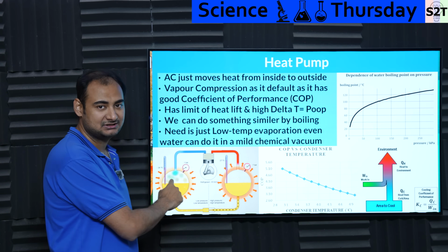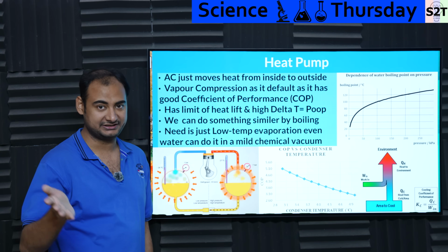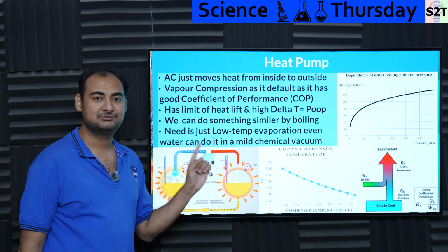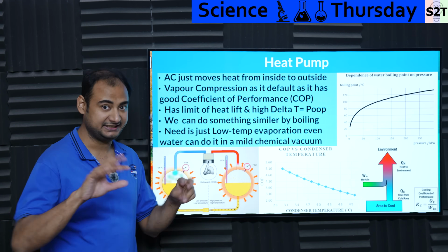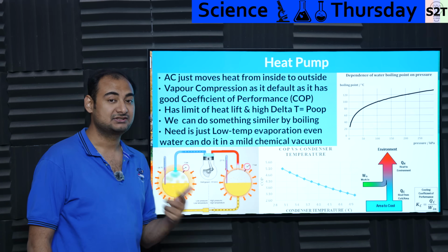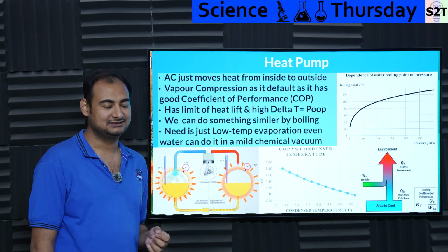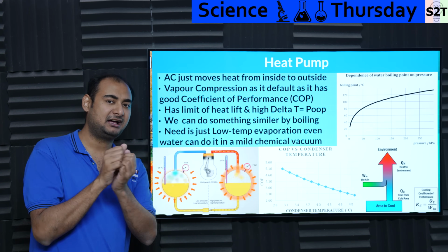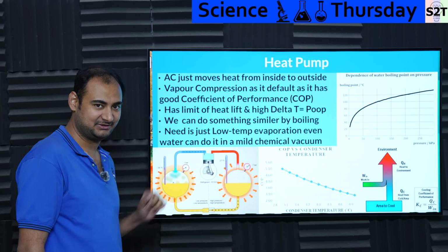Now the heat here was barely room temperature. The heat here is elevated, like 30 degrees, 40 degrees Celsius. At that point in time, you run the fan, it dumps the heat, and voila, now it becomes liquid. But now be mindful, the liquid is not at high pressure at this point, because again, it condensed. It is not under pressure, but it's not cold. If you dunk a thermometer in the liquid, it's not that cold here. However, the liquid goes into this metering valve, and the metering valve allows just a small amount through, and voila, evaporation, and voila, this part becomes cool.